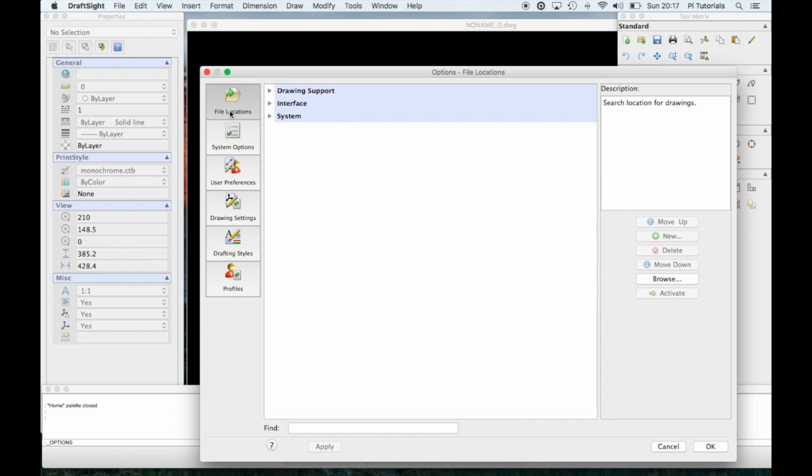So there's lots of options here. I don't get on all that well with Draftsight. The only reason I'm using it is because it's free and it uses exactly the same key commands that AutoCAD does. So I personally can use it very easily. I was using Inkscape, and I still use Inkscape. Inkscape's very good for converting files and doing non-measurement critical stuff, but Draftsight and AutoCAD are excellent when you want to draw something to scale and you want it to be nice and precise.